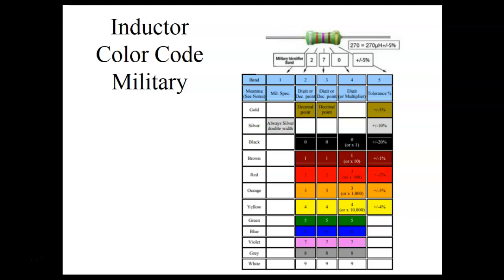Now we can set up a circuit, so this is what we'll use. If I can come up here and put a 1 kilohertz oscillator, and I might have that circuit around there somewhere, using a little timer. We have a timer called a 555. You can use it to time. It's a little integrated circuit, but you can also set it up to oscillate, and it's pretty easy to set up the frequency. Well, if you had a precise frequency like this, we can do this on our trainers over here.